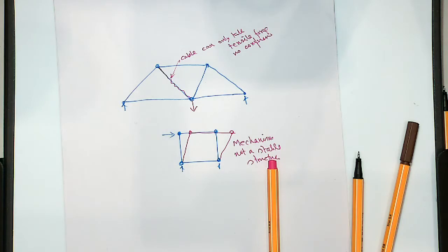How is it 15 times 1 possibility like this one? So let me see, all members are 1 meter, right? So summation of moment about A equal to 0 is here. So that would be 15 times 1 cos 30. And the cos 30, how is it cos 30? 15 times 1, and this angle is 60, so that is 30.